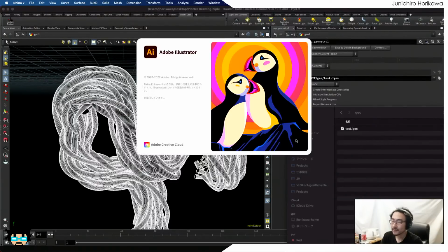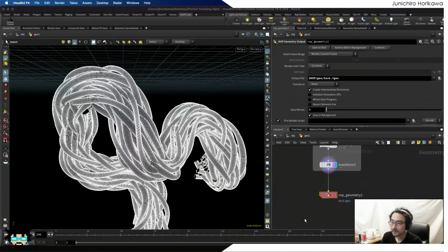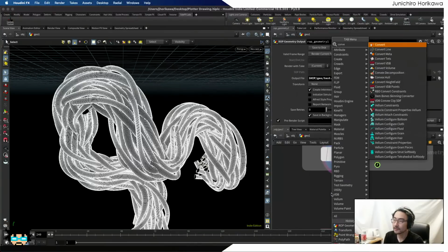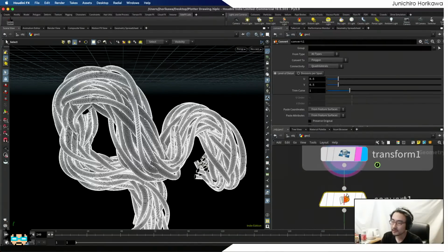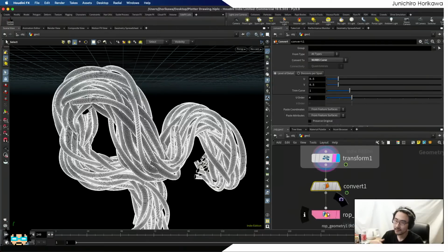I guess using the SVG way is much smarter. But SVG also has some limitations. It doesn't accept the NURBS curve. I mean, you could convert this into a NURBS after this, like using convert to NURBS curve or Bezier curve and export it to IGS.